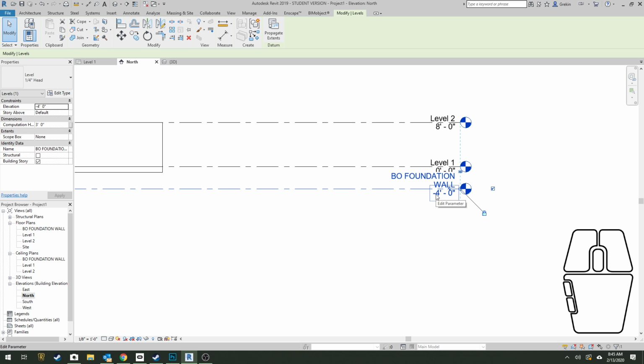Now, you also need to consider your frost depth. What is your frost depth in the area you're building this foundation in? Have you guys done that research so far? Working on this for a couple of days now. Do you guys have the frost depth available? And can you give me a rough number? Is it 10 feet? Is it 2 feet? Is it 20 inches?